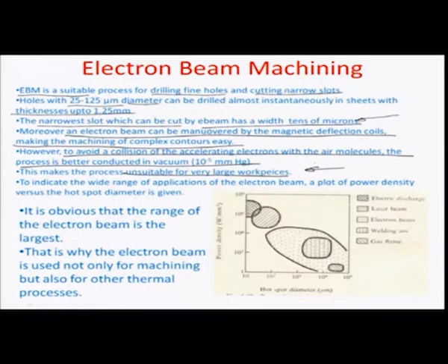And if you look at the way that the different applications can be grouped as a plot of power density delivered to the surface with respect to the hot spot diameter, you can see that for the E beam machining, typically the combination has the largest size, okay, meaning thereby that it works for a lot of hot spot diameters with a wide ranging power density in watt per millimeter square.